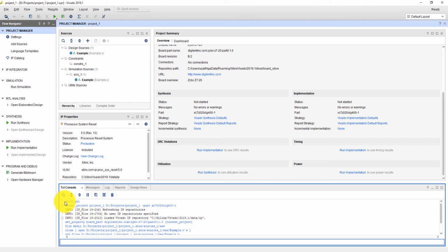Like initially, what we did, we started Vivado. The first command, we didn't write it, but in the Tcl Console Vivado is actually recording everything we click. Behind every option there is a command. So when we double clicked on the Vivado icon on our desktop, it started this command, start_gui, and then we created a project.